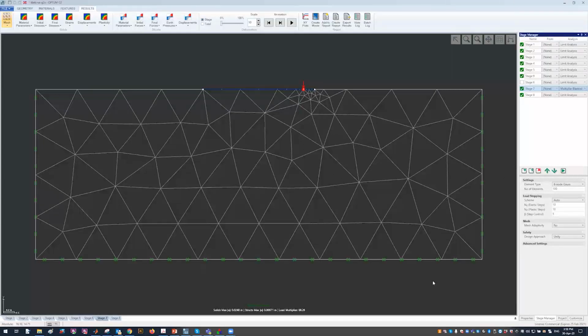I'm happy with that actually, but I'm looking into something, because I really want your opinion on it. Those bearing capacity formulas have been developed for vertical loads and not for horizontal loads. I was always curious as to why they never considered pure horizontal loads. Typically when it comes to horizontal loads, we go back to Ka, Kp, and passive and active earth pressures, and we don't use the bearing capacity formulas. I still don't know why that is the case, why they never looked at that problem, same as vertical loads.